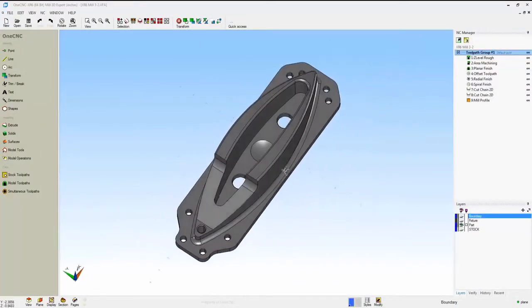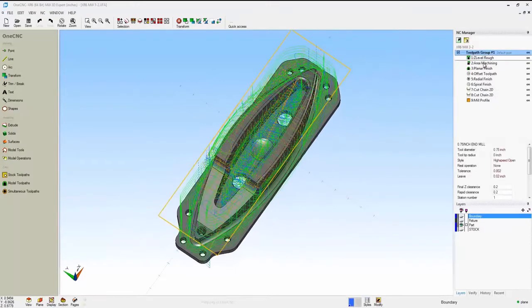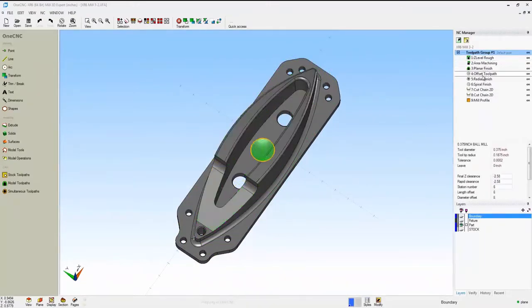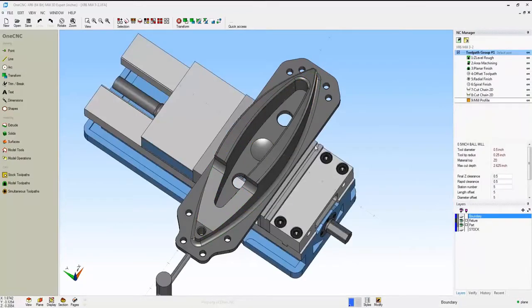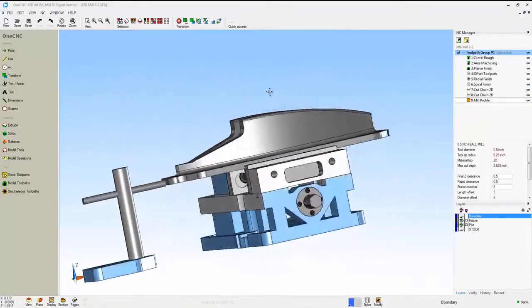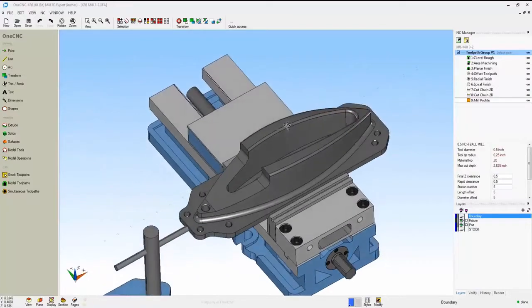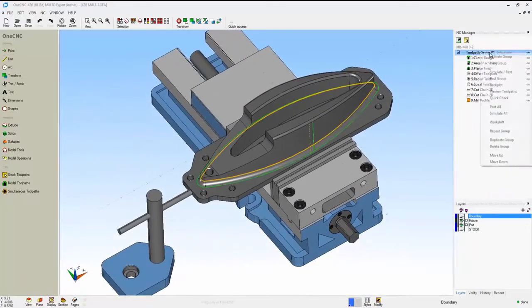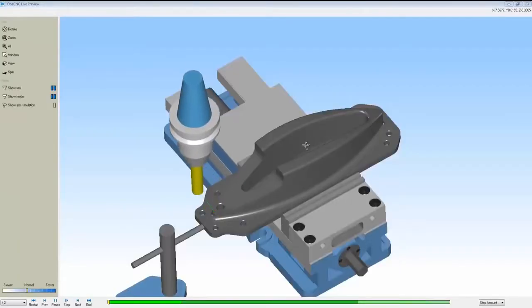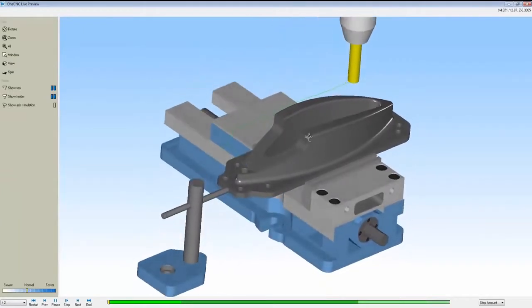Here's another 3D part. Now in this example, again, we've applied some toolpath within the NC Manager. Spiral cutting, radial cutting, and so on. And what we're going to do now is go into preview. But notice now, instead of using a fixture plate, we're using a vise. Now there's really no limit on the detail you can put in here. In this example, we have jaws, we have parallels, cap screws, and so on, and all that information is ported